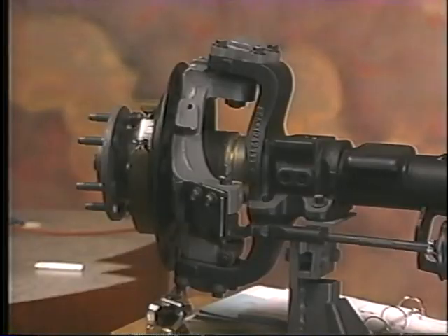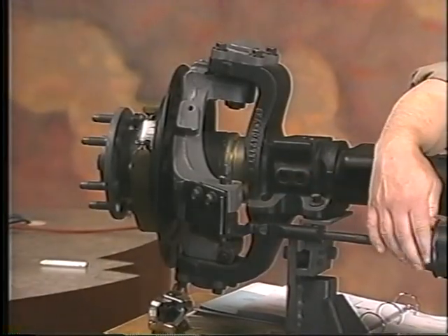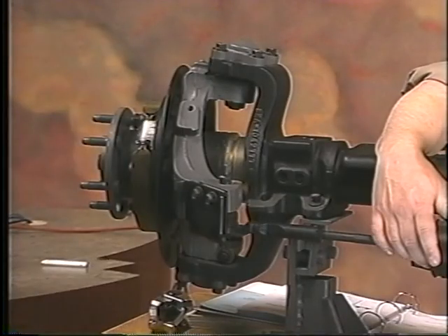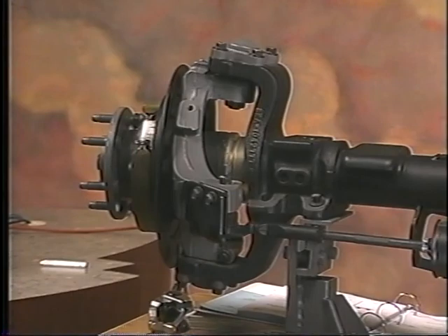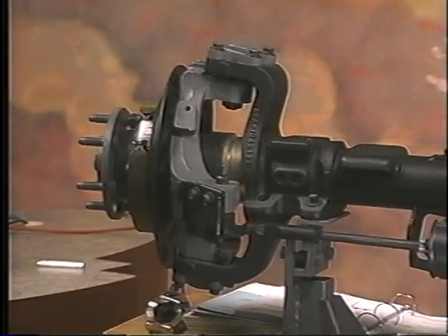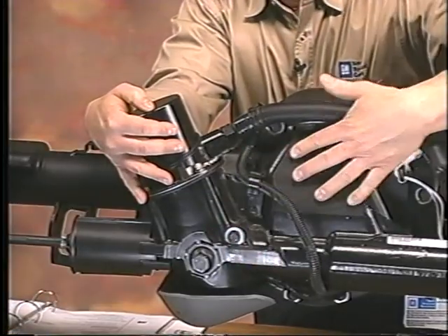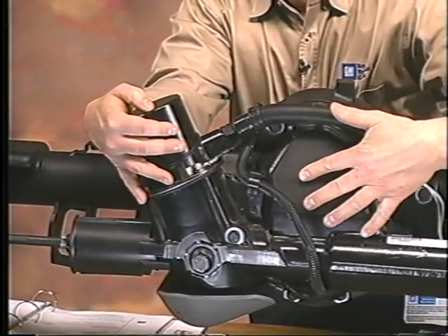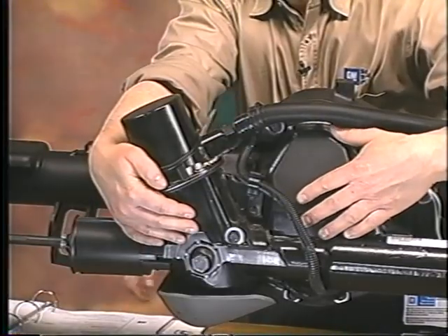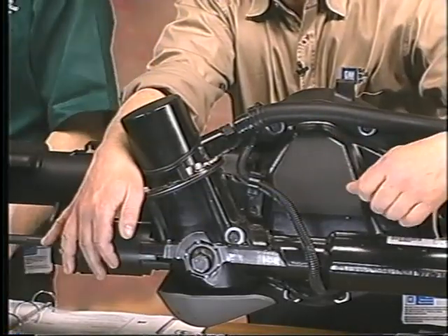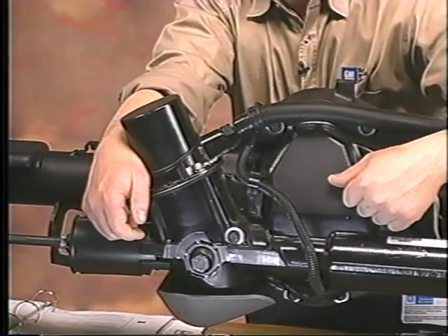Okay? What else we got? Well, we have tie rods. You can see we've got an outer tie rod here. As we start to move inward, we'll be able to see that we have an inner tie rod as well. Inside of the inner tie rod, now we get to the actuator. And the actuator's got a motor assembly. Also, all the assembly right here is part of the rear cover for our differential. So if you have to replace the actuator assembly, you're going to be unbolting the rear cover to do that. You're going to be unplugging the wiring, taking off our tie rod at the outer edge there, and then removing the whole assembly out of there. Right? So some unique features there.